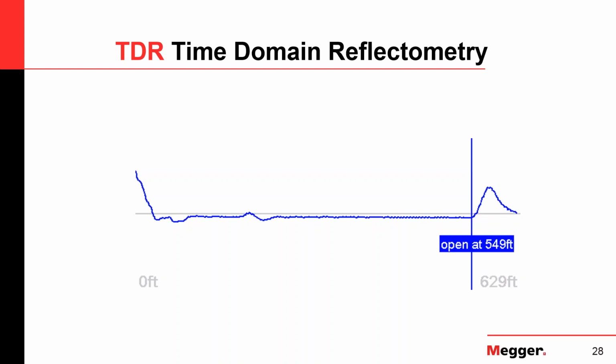Now the thing with this is you can have several systematic errors in there. If you have the wrong cable velocity, then this number will be off. So very important, and this is why I mentioned it's a troubleshooting process. It's not like you hook it up and a magic box is doing the cable fault location for you. That just doesn't exist.